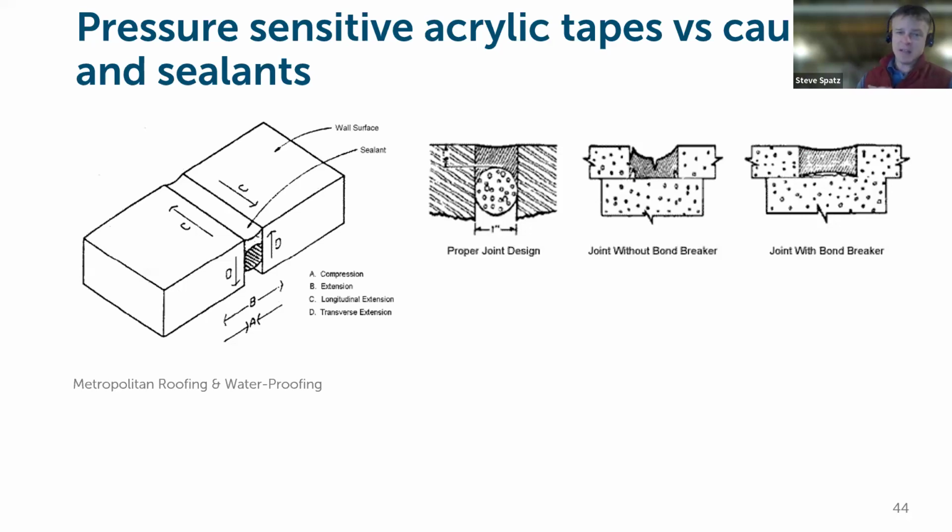So getting back to that, one of the big key things for me is that tape has a lot more capacity for durability than the other things we would have used in the past to seal up these sorts of joints. And what you were just mentioning, Evan, around window and door rough openings, and the transitions between framing to concrete and other stages of the building, is caulking versus tape. Caulk is meant to bridge a gap between two disparate materials that are going to move over time, and stretch when those materials move.